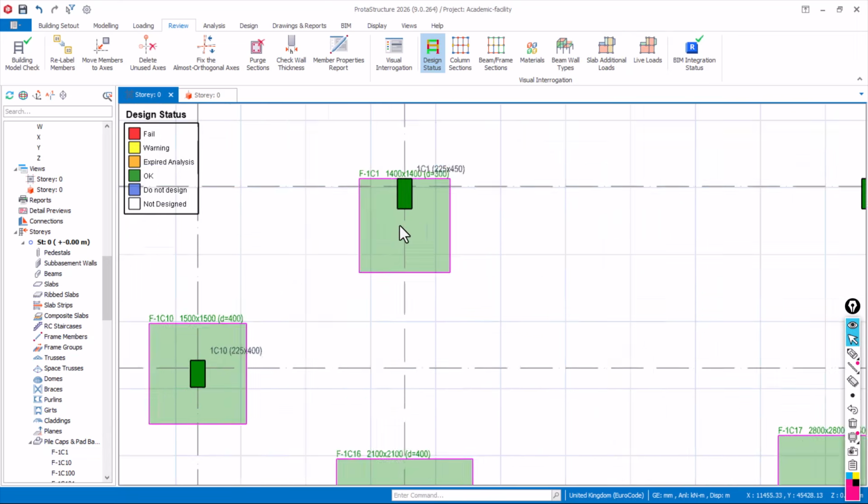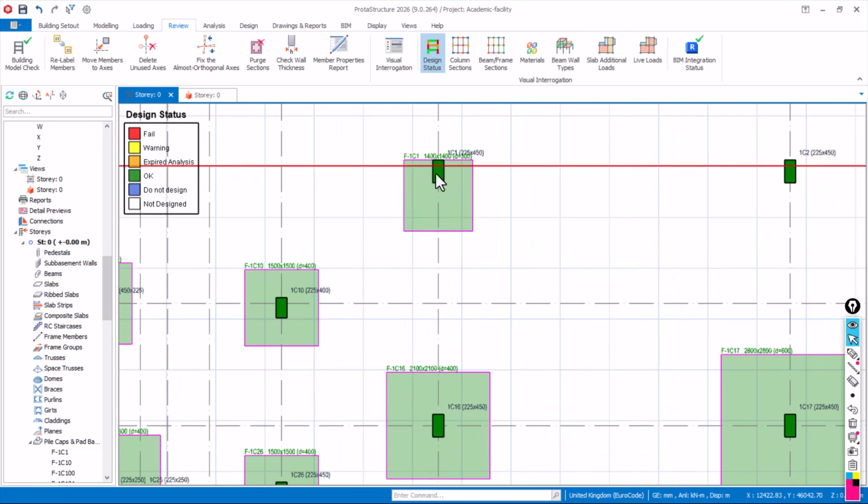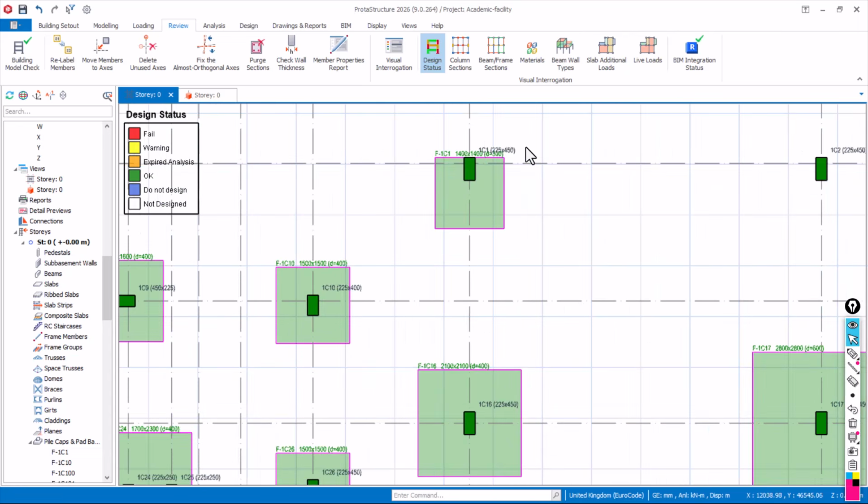It's green, yes, but as it's green, does it mean that it is okay? No, it will fail. If you go to site, it will fail. Why will it fail? Based on the thumb rule, the eccentricity is already more than B over 6, so it will fail. It will fail because there is a turning moment or force happening here, which is causing an uplift and uneven soil pressure within this region. So that is why it will fail.